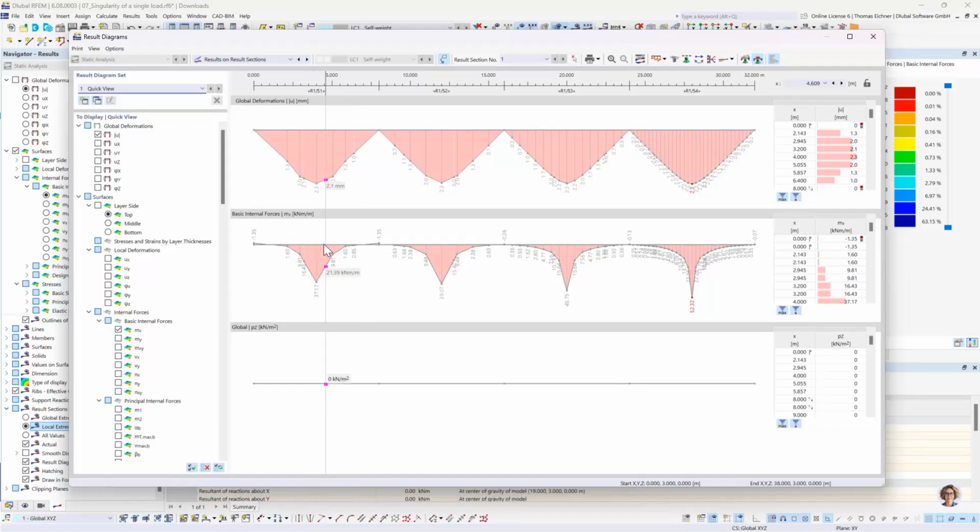Also, if we have a point force somewhere, in reality it won't be a point force. It won't be a needle where some force is going downwards. Mostly it will be like a column of dimensions 0.5 meters times 0.5 meters. Also, we have a thickness of the plate, which means the force can also distribute due to the thickness, and therefore the peak is just not useful anymore.